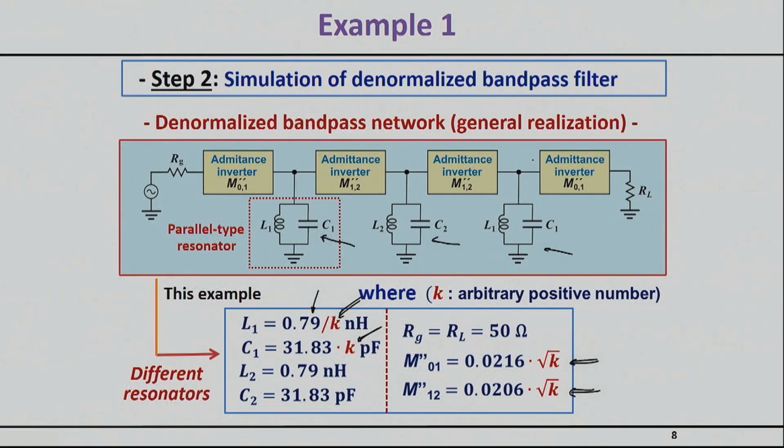Equivalently, it might happen that you don't like these inverter values actually. Why? Because as we'll see later on, they might actually yield an inconvenient impedance calculation, in which case you could go back to this filter and scale everything with a factor of k and recalculate everything. I'll show you, I have purposely chosen an example here to specifically highlight this because it happens so often in real life.